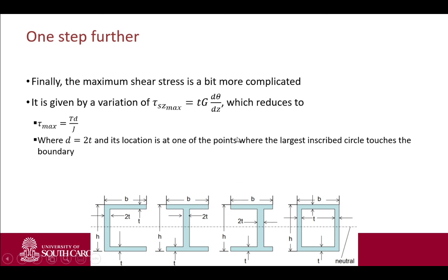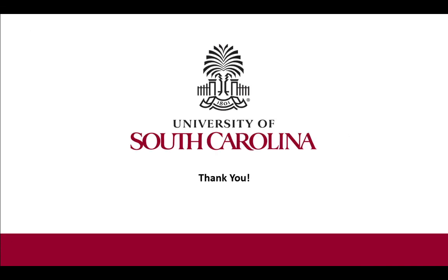But the point is, finding maximum stresses for the bending case was relatively easy, but finding the maximum stresses in the torsion case, where we would evaluate all these structures, becomes a slightly more difficult problem. But then again, based on the cross section, you would already know that you want to go for the closed sections anyway. So with this said, we have now completed three topics: bending, shear, and torsion.